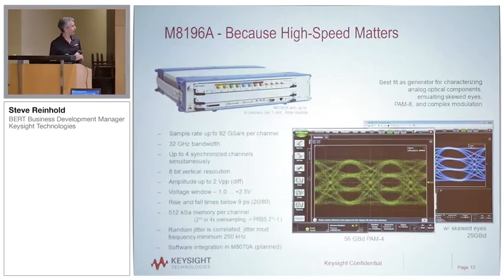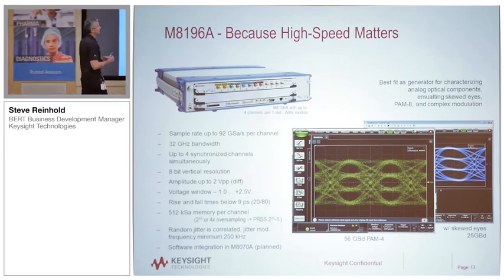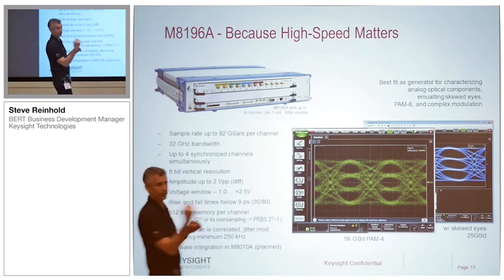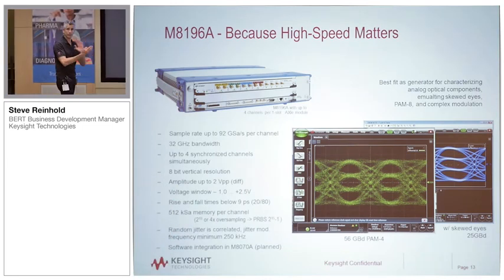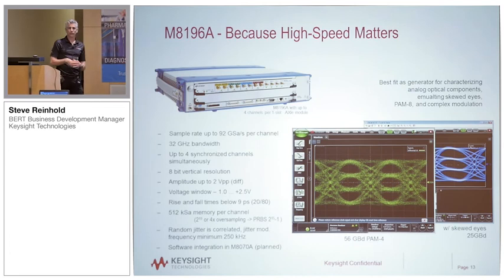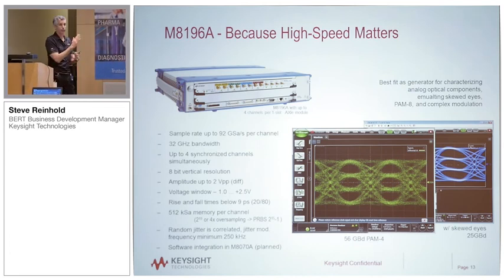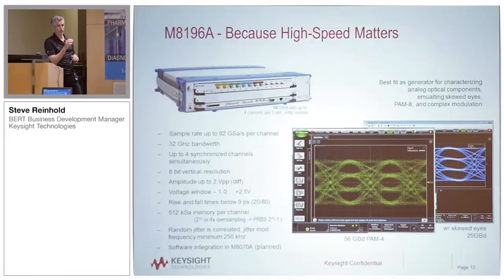The other benefit of AWGs is they can create the skew that we saw in the real transmitter. You saw it was skewed horizontally. With the BERT generator, we can skew things vertically with the linearity test, but the horizontal skew requires an oversampled architecture like an AWG.